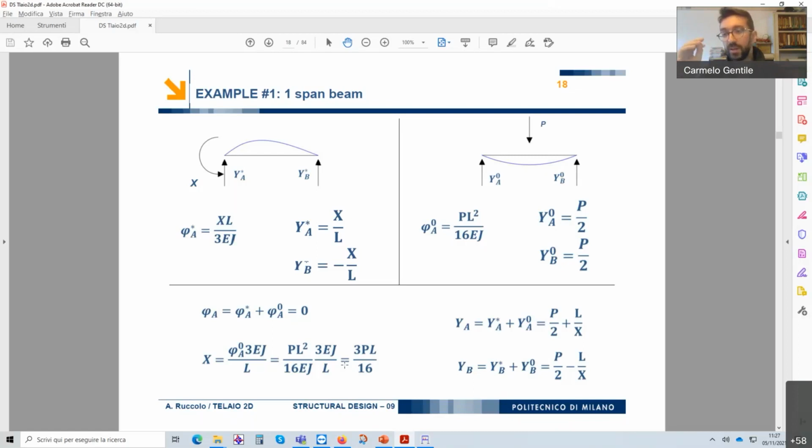If the structure is statically determined, then the distribution of forces will never depend on the distribution of stiffness. Why? Because we can only use equilibrium equations. If we use only equilibrium equations, we have no iota popping up.